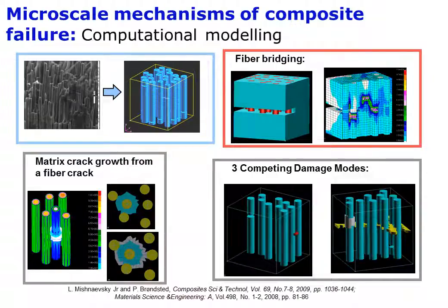An example of this is the simulation of damage mechanisms in fiber-reinforced composites under tensile loading. We simulated the fiber debonding, fiber damage, and matrix cracking. In the computational simulations, an interesting observation was made, namely, that weaker and softer fiber-matrix interfaces can prevent matrix cracking in composites.